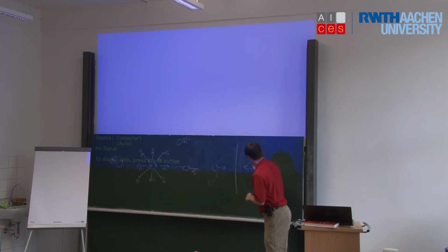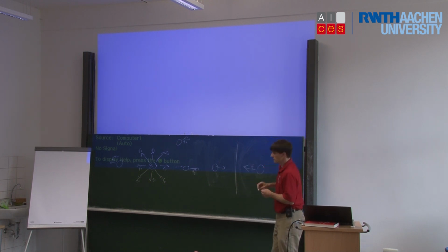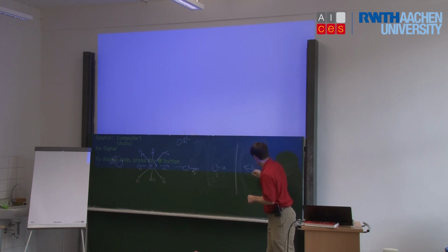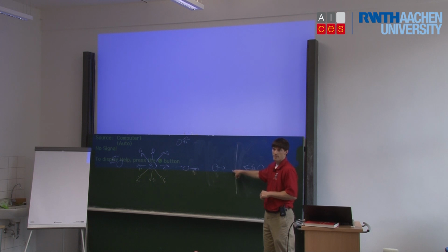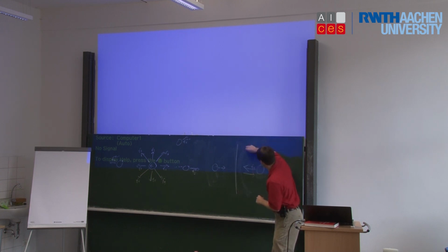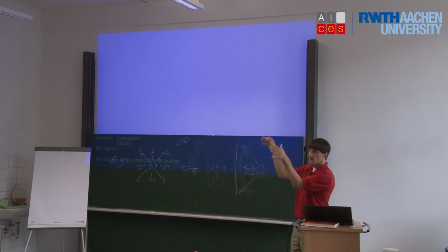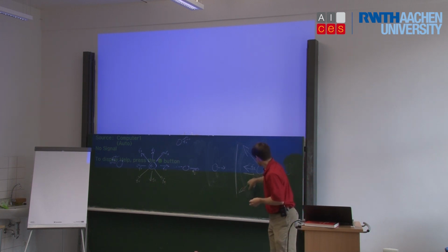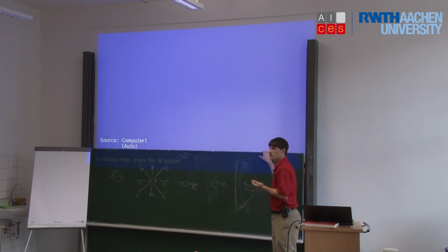This F, the sum of all F values that travel in the x direction is really the x momentum. Okay? So if this F, in this case this would be F4, hits this wall and is reflected, that really is a momentum exchange at this boundary. Okay? So if I sum this F and that F value up over this wall, that's the force that this wall experiences along this link. Now there's an additional force along this link and along this link at the boundary. But basically, in essence, what I can do is I can identify all boundary points, and I can then sum up the forces or sum up the distribution functions that interact and bounce back from the wall in order to compute or evaluate the total drag on the surface.